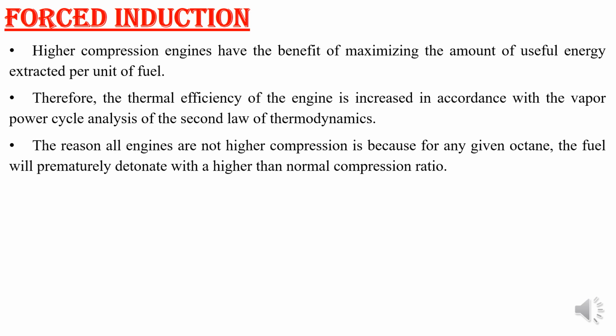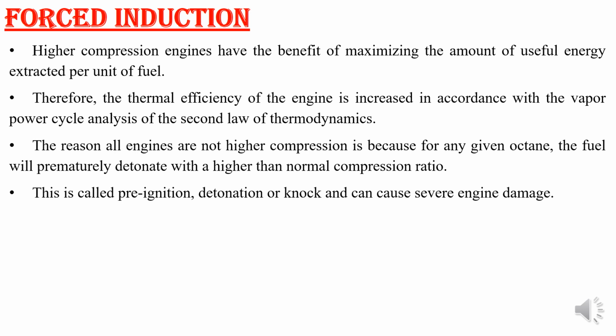For that reason, we can't go for a higher compression ratio. That is one thing we can note down, because a higher compression ratio cannot be used because of the knocking limits of the engine, because that may lead to pre-ignition or other kinds of damage to the engine materials.